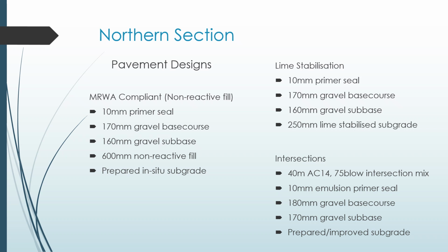Now, the Main Roads compliant design, which is the 600 mil of non-reactive fill over the in situ silty clay, obviously with the design CBR of 10, results in our primer seal, 170 millimetre gravel base course, 160 mil gravel sub base, and the 600 mil of fill on the prepared in situ subgrade.